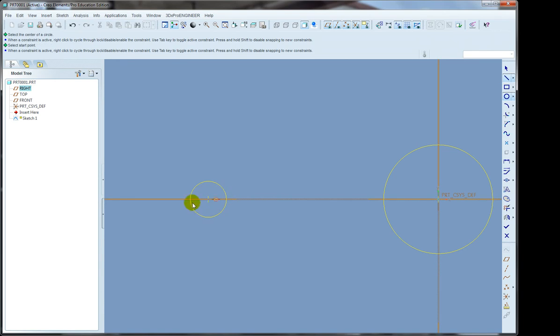I'm going to connect the end point of this circle and the center point with a line, because that's going to be something that's important to me later. Now, the back side of this has a diameter of 1.25, and the circle that I'm using in here has a radius of 1, so I'll make the diameter 2, and 6.5 is the distance between the two. So by laying out all that information, I've gotten pretty close to where I actually want to be with this information.